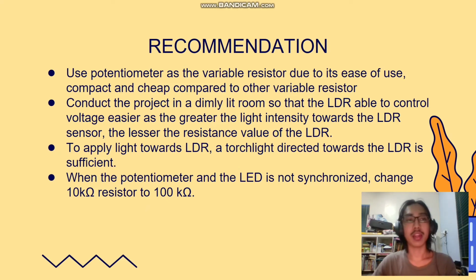Okay, as for recommendation, we recommend the usage of a potentiometer as the variable resistor due to its ease of use, which is you just twist it to control the voltage, compact due to its small size, and cheap compared to other variable resistors such as the rheostat. Next, if possible, conduct the project in a dimly lit room so that the LDR is easier to be controlled,